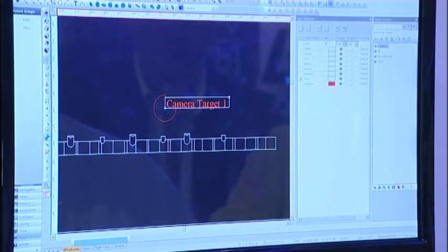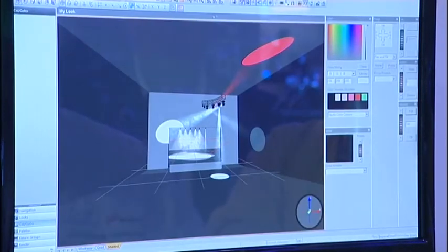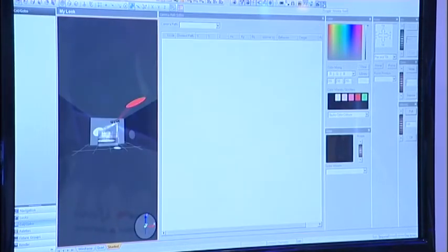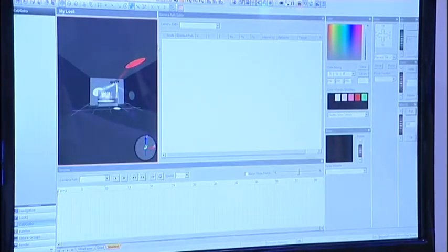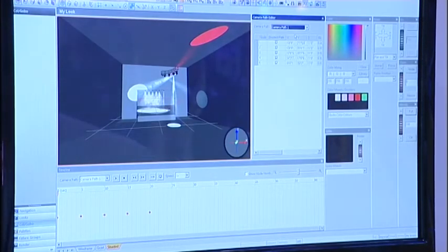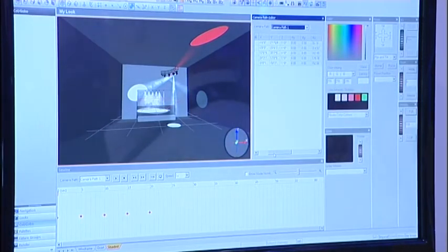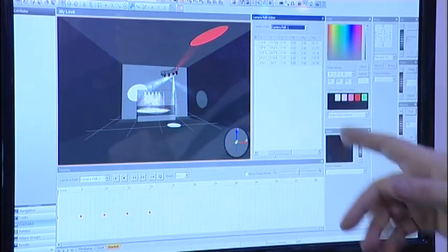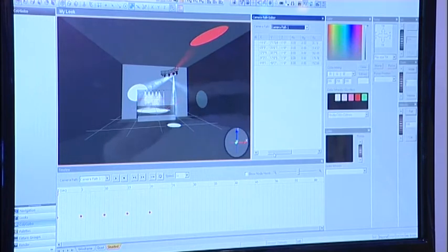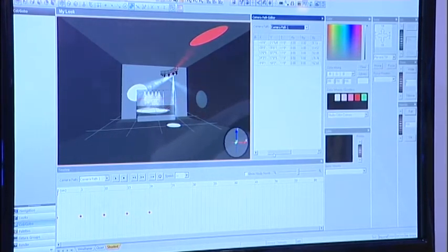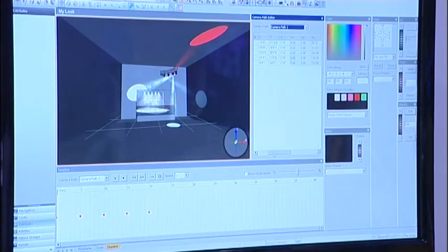Okay, I'm going to go back into design mode. And I'm going to turn on my camera path editor and my timeline. I'm going to scoop this a little bit back this way. Okay, camera path. We give you the ability to change nodes on X, Y, and Z positioning. In R29, we also give you information on roll on X, Y, and Z. So roll, pitch, and yaw, or roll, pitch, and bank, heading, stuff like that.